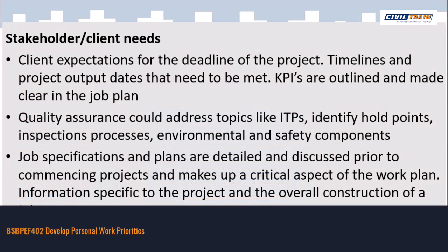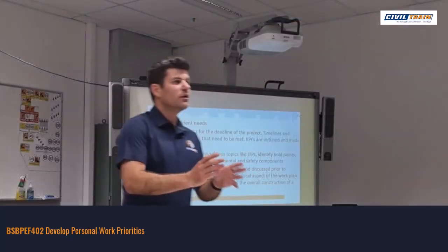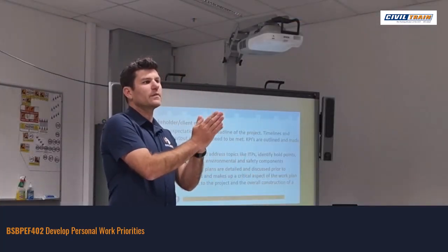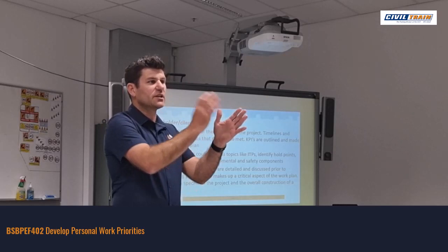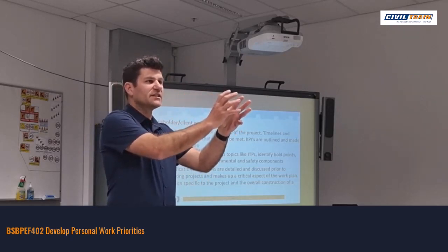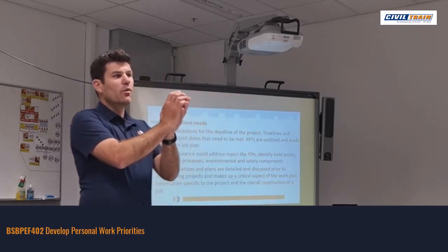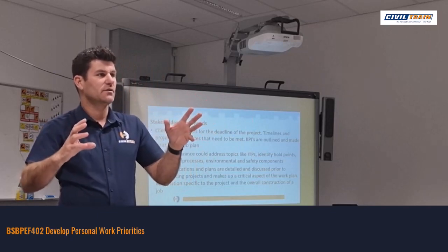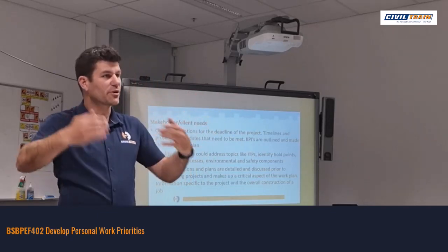Quality assurance, often or not ITPs, so inspection test plans. So with the quality assurance, often when you look at a specification, you might actually find that there's certain control points or witness points that need to be put in place that all of a sudden now prevent you from your normal dependency line, because they've thrown something in where it needs to be inspected by the client, which normally you would just progress with your works.